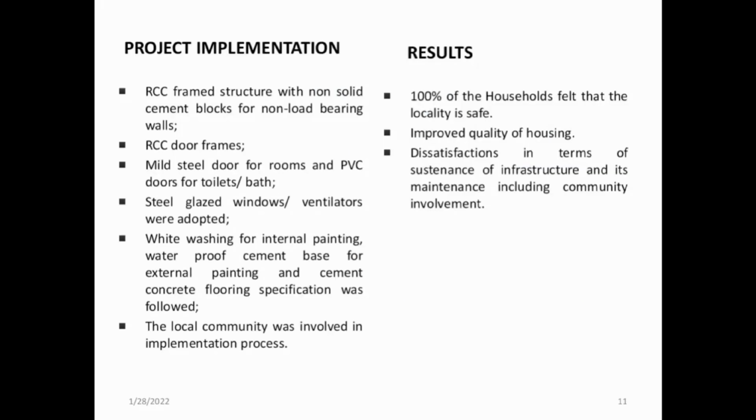In this project, an RCC frame structure with non-solid cement blocks for non-load bearing walls was adopted, which is light in weight and has a low cost of production. RCC door frames were adopted since they are eco-friendly, fire-resistant, termite-proof and have a longer life. Mild steel doors for rooms and PVC doors for toilets and bathrooms were adopted. Steel glazed windows and ventilators were adopted for cost effectiveness. Whitewashing for internal painting, waterproof cement base for external painting and cement concrete flooring specifications were followed.